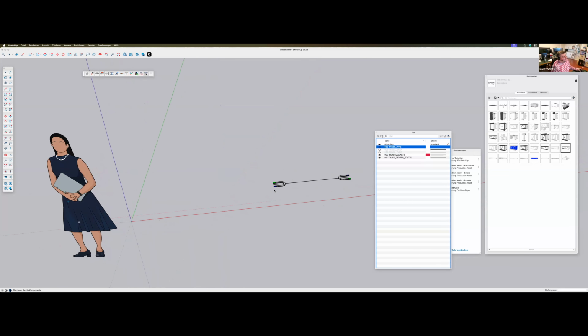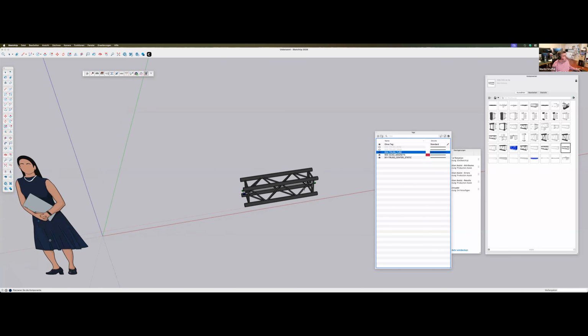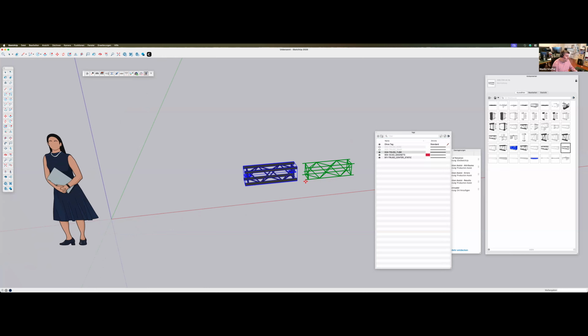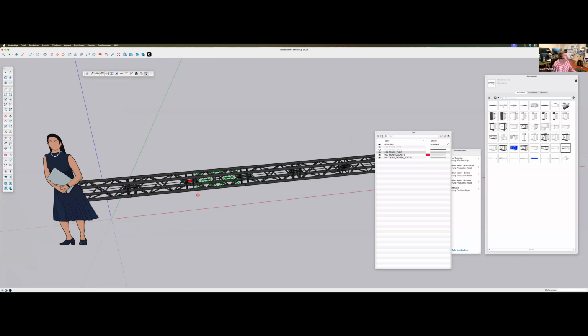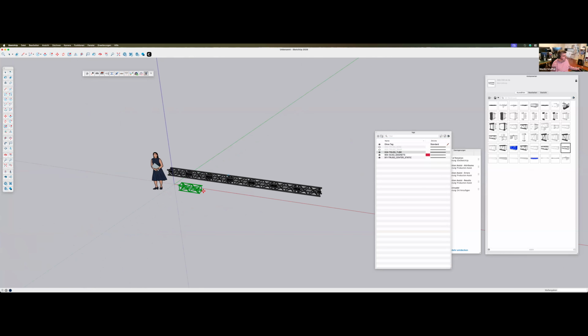The most important part, which will actually be used for structural calculation, is the middle line of the truss, together with two magnets that will be used for the snapping functionality that we will show you. Those magnets allow you, if you click on one truss, to activate the magnet tool. Select it, and you see you have it attached to the mouse. Then, if you hold the Alt key or the Option key once, you can use it to duplicate the trusses. So really easy. You can align them and add one truss after another, like a truss run, and create the truss that you want to calculate.